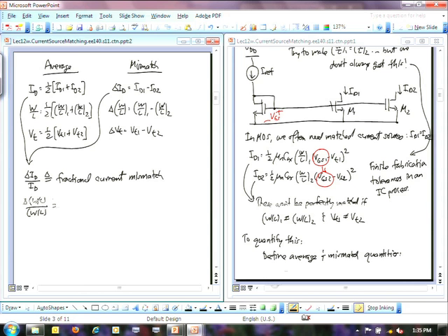Interesting equation now, because this is telling me how much mismatch I'm going to have in currents. Okay, so the way to interpret this here is that this is my fractional current mismatch, a quantity that can be used to compare one current source design, for example, with another one, on how well matched their currents are.